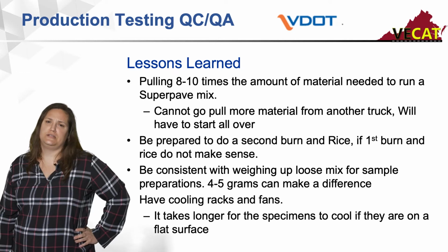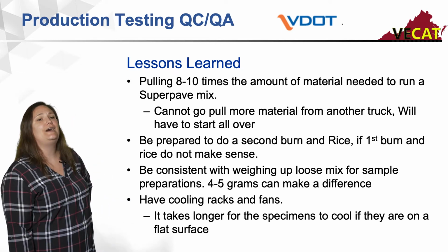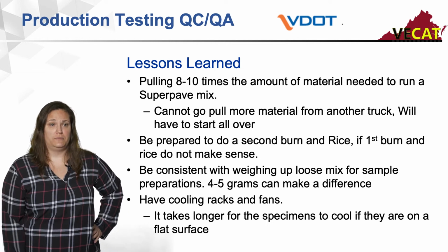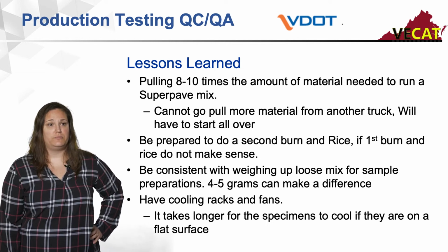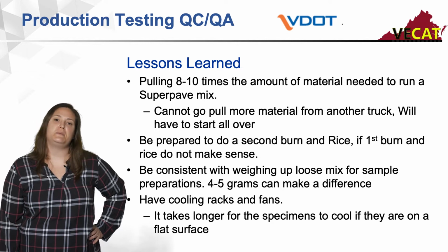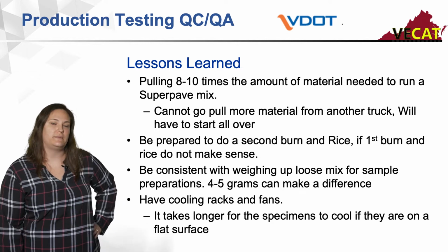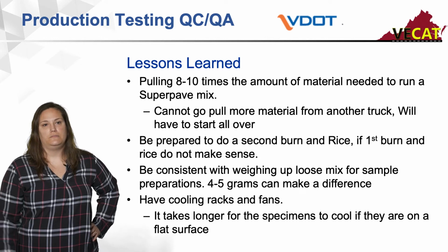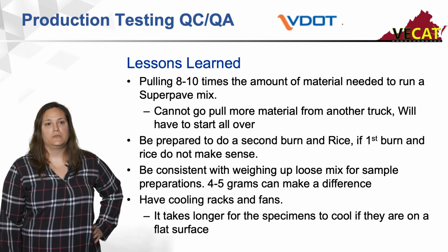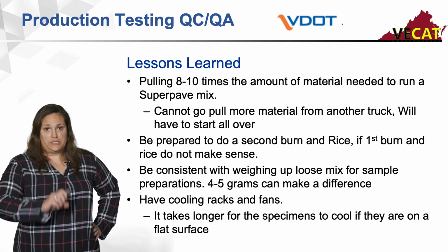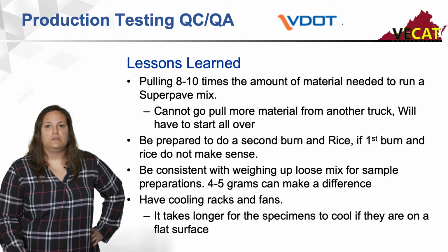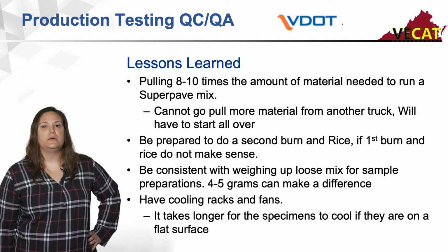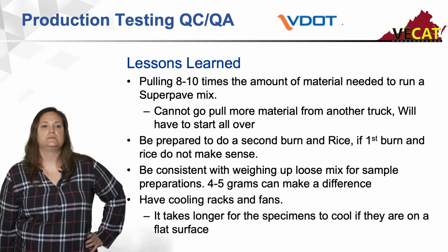Some of the lessons learned: make sure you pull enough material out of the first sample that you're pulling. If you need to pull extra bags, extra buckets, boxes, however you transport that sample back to your lab, do it, because you can't go back for more. Once it's gone, you basically have to start over. I would definitely suggest, if it's your first time doing it, go ahead and pull those extra ones, so while you're trying to find the right weight for your pills, you don't run out of mix.